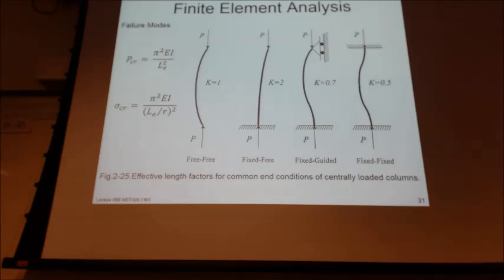If we're dealing with a short column, then you're going to use Johnson's formula. And when we're doing FEA, the buckling problems will be non-conservative for columns that are not Euler's equations. However, as long as the operating stress on the non-Euler column remains below the yield point, then buckling failure is not possible. Eccentric loaded columns require that we use the eccentric loading column equation.